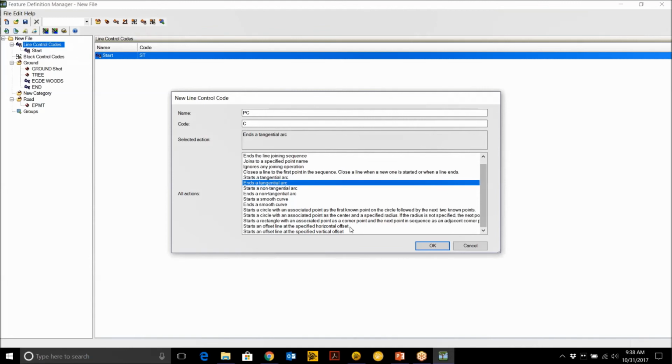Okay. I have a question that just came in. Can you do a template code shot? As an example, if you would shoot the bottom of curb, could it also draw the top back of curb and the sidewalk and the front and back of sidewalk by just taking one shot? So I would interpret that to be, can you do multi-codes from one shot? If you took a gutter shot, could you start a line and offset a line and potentially do multiple offsets from taking that one gutter shot?